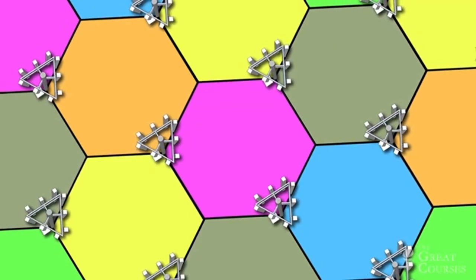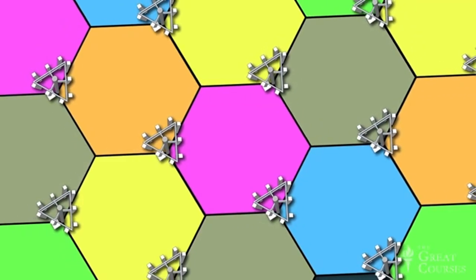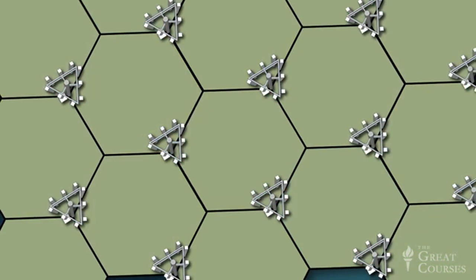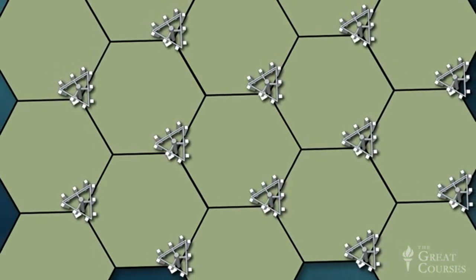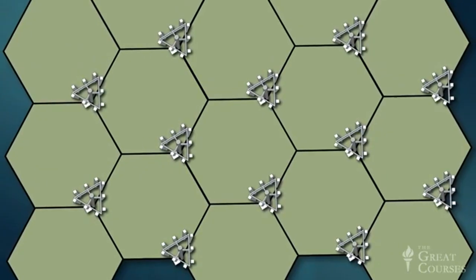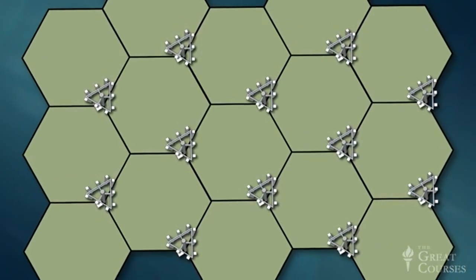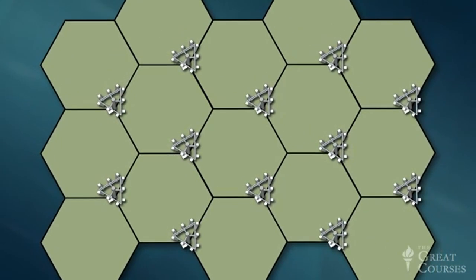And in a cell network, this system uses electronic spectrum 10 to 20 times more efficiently than the simple frequency division scheme used in 1G networks. It also produces further increases in capacity by reducing the cellular reuse pattern to 1. In other words, the code division multiple access system allows for adjacent cells to operate on exactly the same frequencies without interference, as long as these adjacent cells use different codes. This feature represents another 7-fold increase in the number of users per cell in comparison with the reuse pattern of the 1G network.